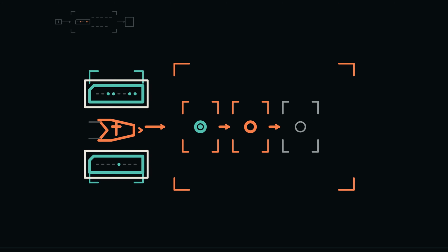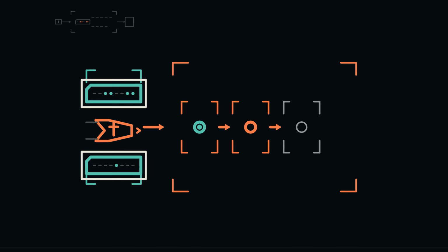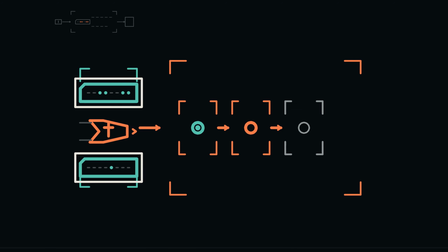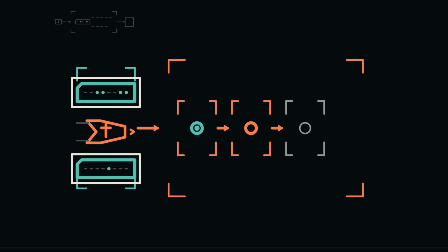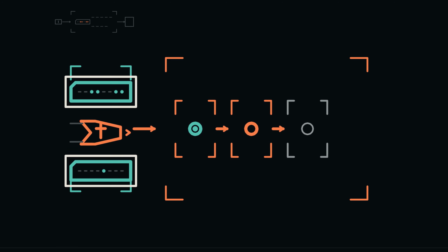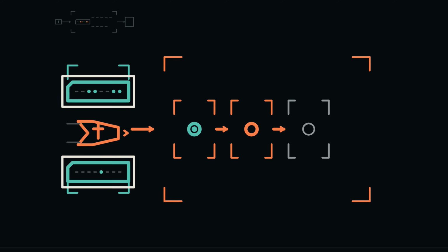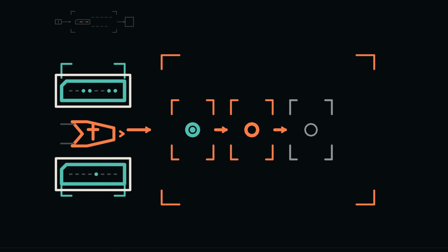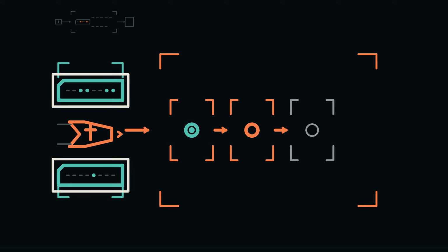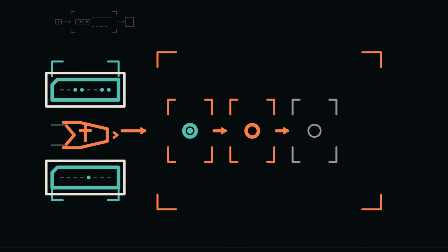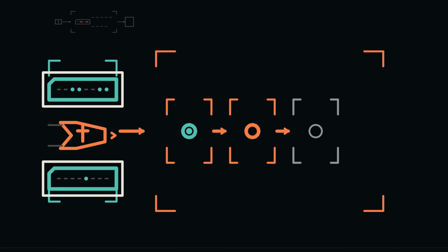SE8 completes fetch, decode, and execute steps in an easy-to-follow sequence. A pipeline overlaps stages belonging to different instructions. While one instruction executes, a later one may decode and another may be fetched. This is like an assembly line only in the limited sense that different stages work on different items at the same time. Instructions are not identical products, and dependencies can force the pipeline to wait, redirect, or supply a result from a later stage to an earlier consumer.